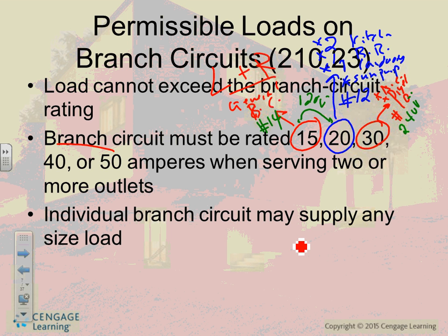What do we use these for? The range. Fixed standalone range, big range. What size wire do we use? You gotta remember, we're going to range. What voltage? Always 240. 230, which is 240. That's it. If you guys know this, you have known all the branch circuits in a dwelling.